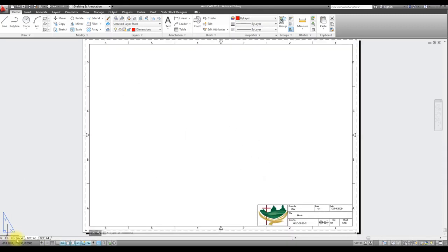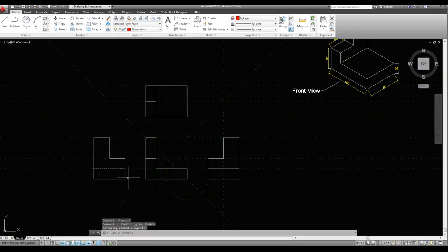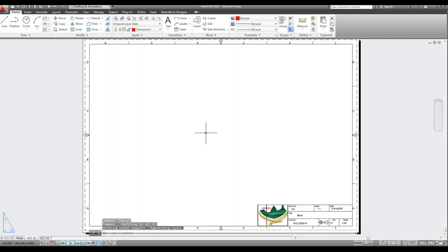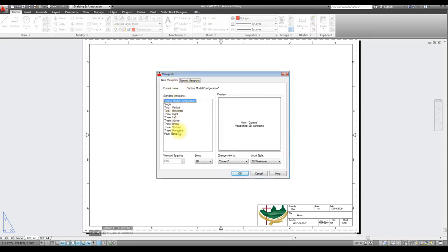Now we've got a sheet of paper here and we've got model space. We've got our geometry in model space. We've got to somehow be able to look into model space. What's the easiest way? Cut a hole in the piece of paper, basically. That's what we do. It creates a window, like the portholes on the side of a ship so you can see from inside to the outside. We have a viewport, and we just type into the command bar viewports, and it brings this dialog box up, which gives us a choice of different viewports or styles we can have.